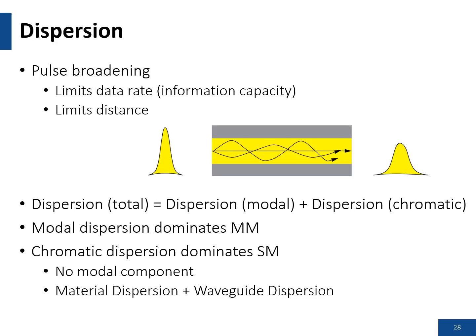The other value that we're going to talk very briefly about, because you can go into a lot more detail about it, is dispersion. Dispersion limits basically the maximum bit rate you can transmit in a system, or the maximum amount of bandwidth that you get from point to point. What happens is the pulse starts to broaden, and it broadens past the duty cycle, and starts causing errors.